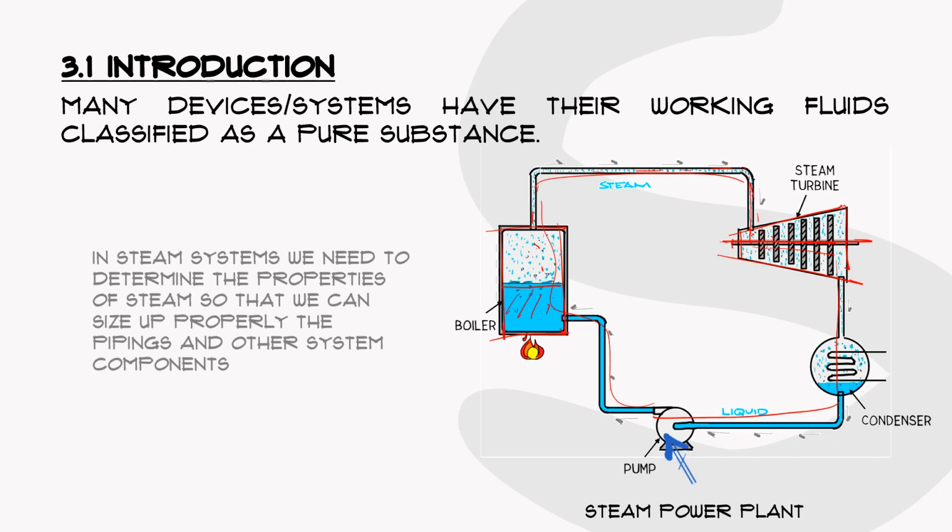So the energy in the steam will cause these turbines or the shaft to rotate. So that means we have this mechanical output power here. And if we attach an electrical generator, that means we can have an electrical output as well. So steam will enter the inlet, and then will cause this shaft to rotate, and then it will exit at this point, at lower pressure, because some of the energy is already transferred to rotating the shaft,